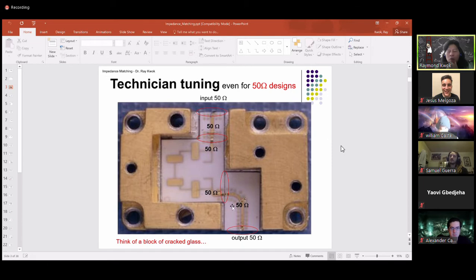Well, the circuit is not working because, so this is a 50 ohm line. This is a transmission line, 50 ohms. Going into here, coming out here is also 50 ohms, and 50 ohms goes out. But the problem is, you see how this circuit is laid out in 3 pieces, right? Every time you have a junction, when the signal is coming from here and here, at this junction there's a discontinuity. That gap here is not a 50 ohm line. That's not 50 ohms. So now you're going from 50 ohms to something we don't even know what impedance it is. A lot of the signal would be reflected back. And when we go to here, it's the same thing.